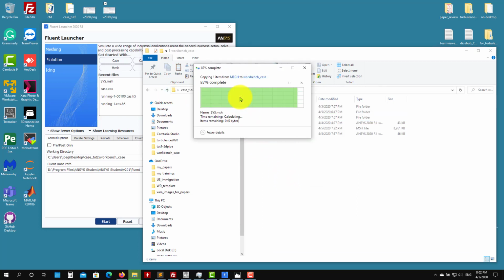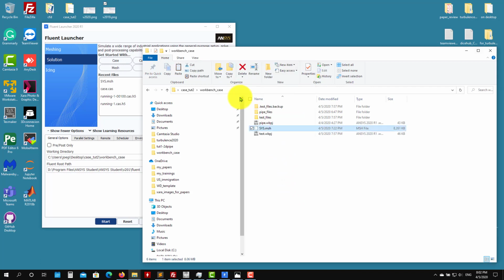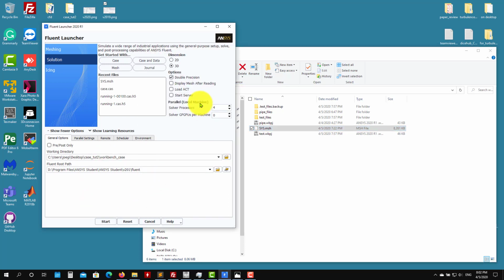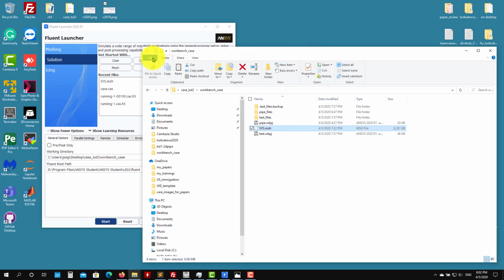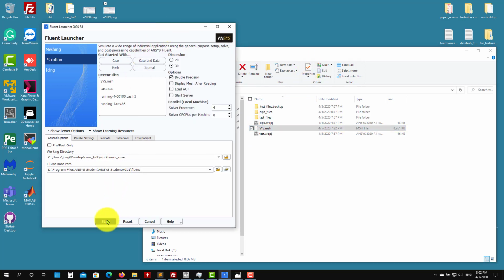Okay. So I assume here that I just use workbench to create the mesh, and then outside that workbench I don't want to have all that data structure. So launch Fluent. Remember, now it's a standalone. So you need to say that it's a 3D mesh, number of processors, then give the location of the folder. Okay, and you start. From this point on, everything will be exactly the same. I will just show you a few steps, but nothing changed, okay? As we did the setup from inside the workbench, we're going to do it here, but we just need to read the mesh.